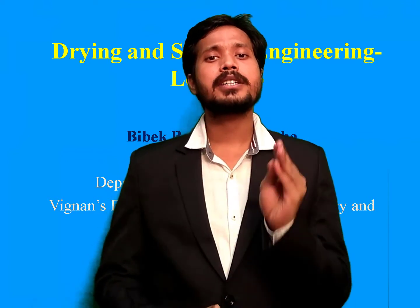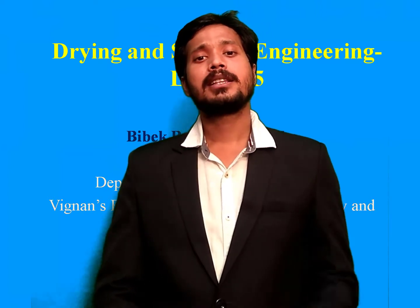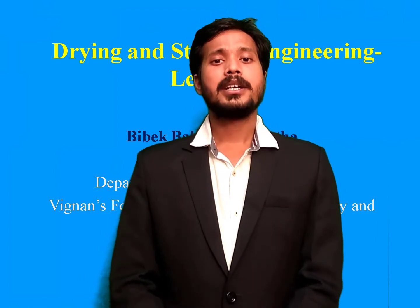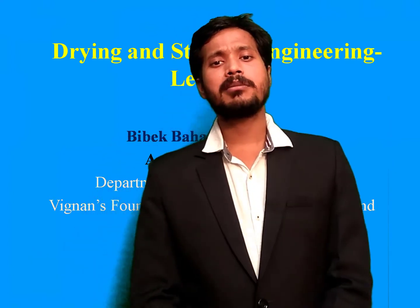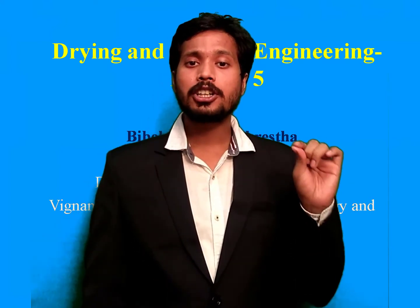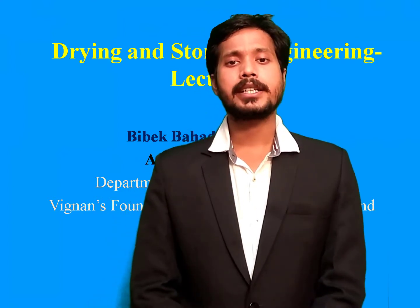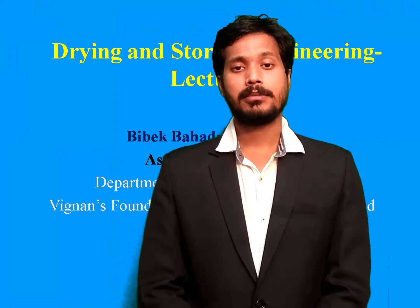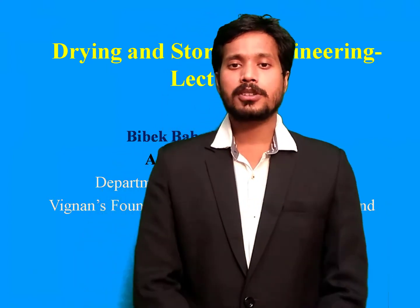Hysteresis effect means that at a particular relative humidity, the value of desorption equilibrium moisture content and the value of adsorption equilibrium moisture content are not the same. In the equilibrium moisture content versus equilibrium relative humidity curve, the difference between desorption equilibrium moisture content and adsorption equilibrium moisture content at the same relative humidity is called the hysteresis effect. Okay, so up to this I think we have discussed. If we proceed further,